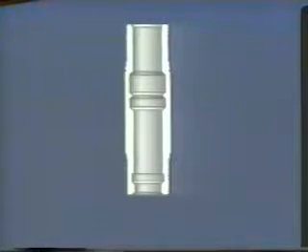For every selective nipple system, there is a compatible no-go nipple that is designed to be used with it. A no-go nipple is a nipple that has a restricted ID as compared to the selective nipple of the same nominal size. Because the nipple is restricted, only one no-go nipple of a given size may be included in the tubing string, and it must be run beneath all selective nipples of the same nominal size for the completion to be compatible.